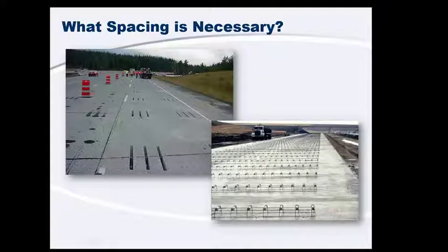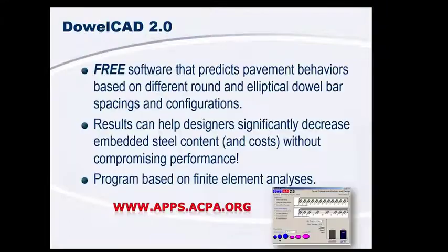So if you actually come in here and you remove some of these dowels in the center of the lane where they're not really doing much good, you can actually save significant money over the course of a project.